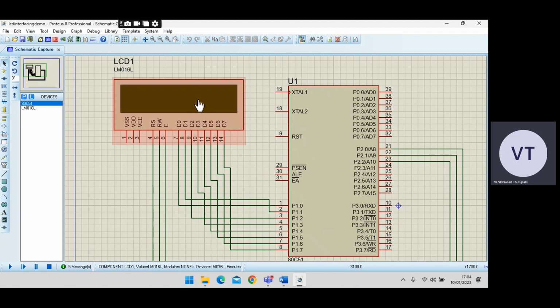I'm going to design an LCD display. I'm going to interface one LCD unit to the microcontroller. My intention is to display Sainik Puri or some text on this display unit. In order to display the text, I will write a code in Keil simulator, and I will generate one hex file. That hex file I'll put in this microcontroller. So this is my target.